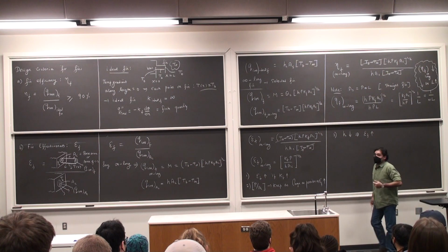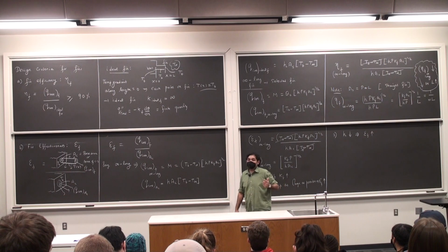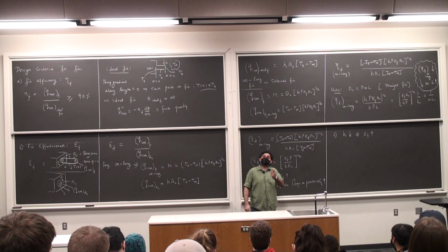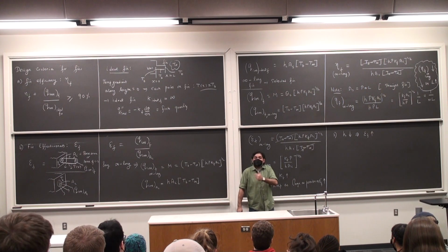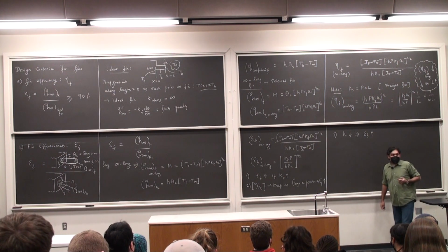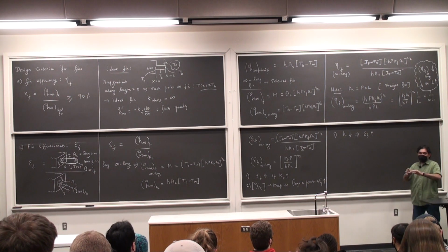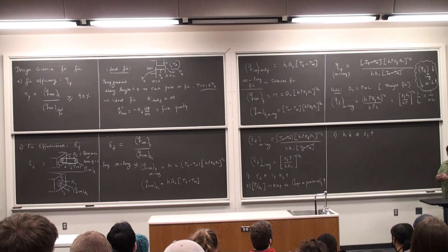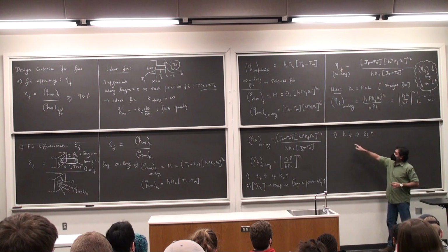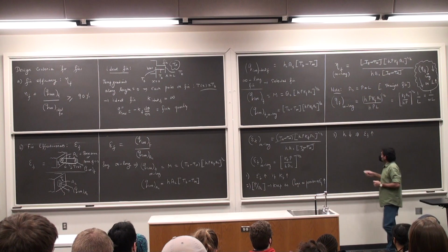Okay? And another thing, if you're using forced convection with fins, that's not a good idea, because if I'm using forced convection, H is larger than in the situation for free convection or natural convection. So that is why you don't want to have a big blower sitting and blowing air across your fins. That is just going to increase H, which will decrease your effectiveness.